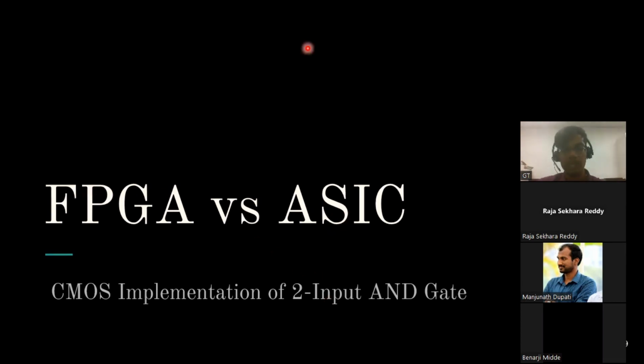How was the DC bus created from the output of the converter? Are ceramic capacitors used for filtering? Yes, the output capacitor is to take the ripple. The inductor current will have ripple, so the output capacitor is connected considering the ripple requirements and also the transient. Depending on that, the output capacitance is selected, and we use ceramic capacitors, and we connect multiple of those capacitors in parallel to reduce the ESR.